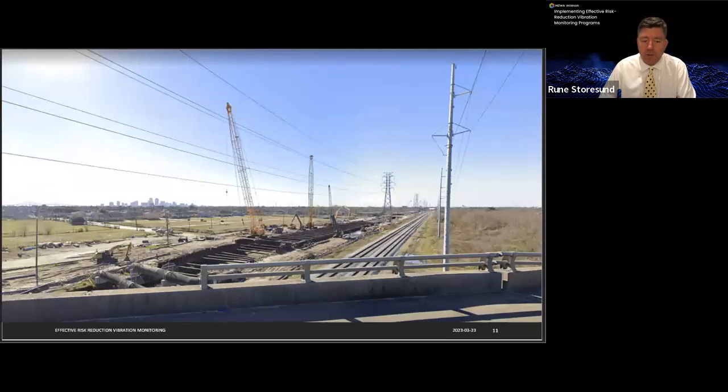Now, this site is very different from the previous one we looked at. There are some residential structures off in the distance, but the project site is not situated immediately adjacent to structures. For this type of project, we'd probably want to be sensitive to the access routes used by the construction equipment and supply trucks if those trucks and equipment access the project site through the neighborhoods. It may be that your greater risk vulnerability is going to be associated with the construction access portions of the project as opposed to the primary construction work itself.